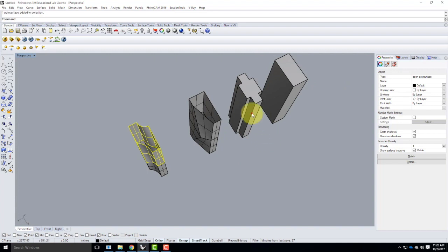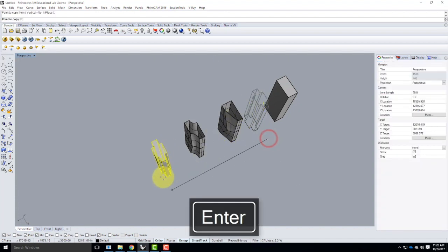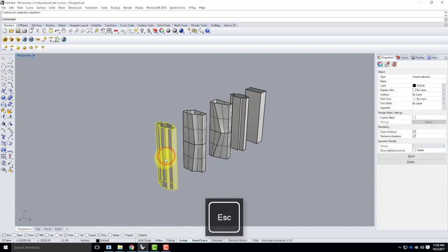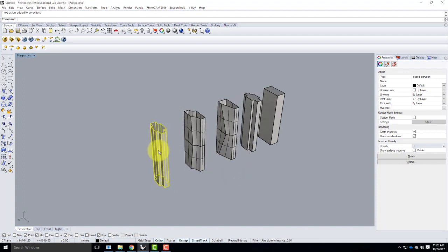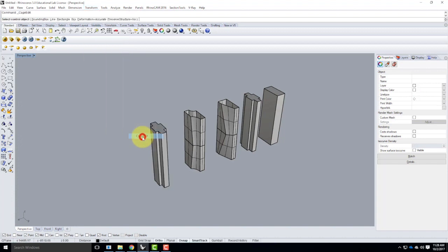So sometimes you want to take a shape and change its complexity where it started from and then maybe make it twist. So let me take this shape again. And I want to transform this so that it twists. So I could, of course, have a top and a bottom, and I could rotate the top versus the bottom or something like that. But I can also use something called a cage edit. And a cage edit will transform this using a set of control points. So if I go up to transform and I choose cage edit, or excuse me, cage editing and then cage edit, you can skip create cage. It just separates it out into 2 separate commands. It's easier to just do cage edit.